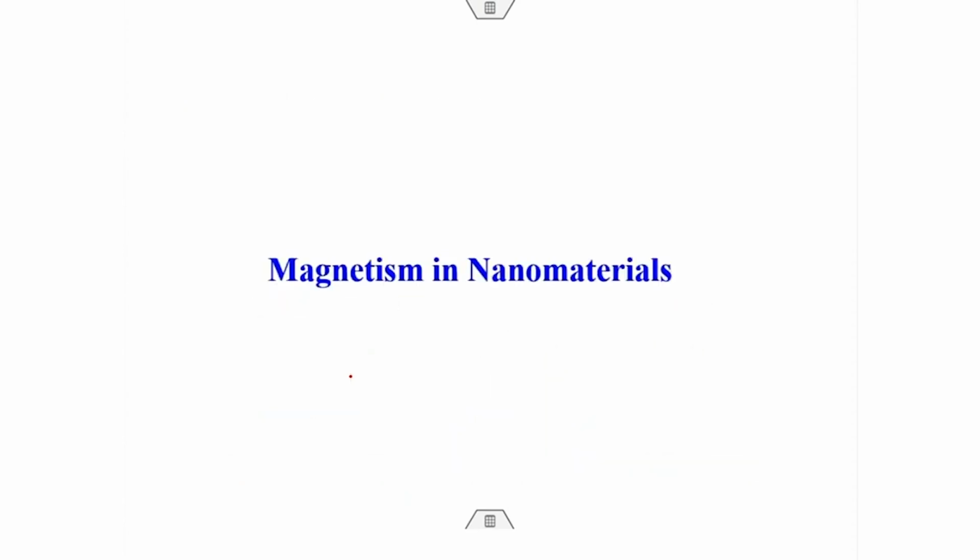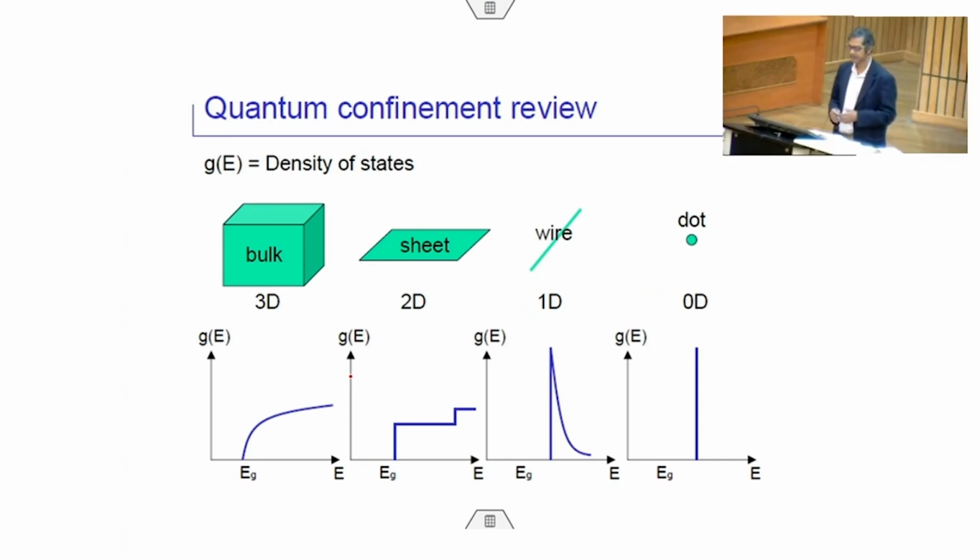Well, that dictates the things happening in the 1D, 2D and 0D nanomaterials, the electronic conduction, that is the primary thing. Now, whenever talking about such things, what is important to consider is what kind of contacts it will make. For 3D nanomaterials or maybe 2D, the contacts will be ohmic contacts. But for 0D and 1D, the conduction from the contact to the material will be given by electron tunneling, and we discussed that in the last lecture.